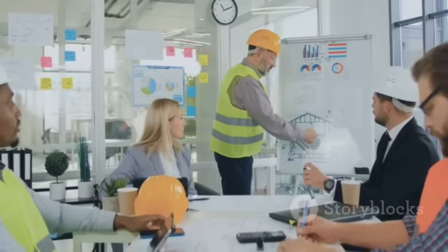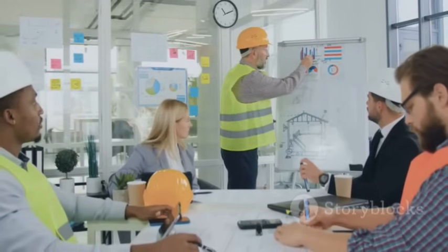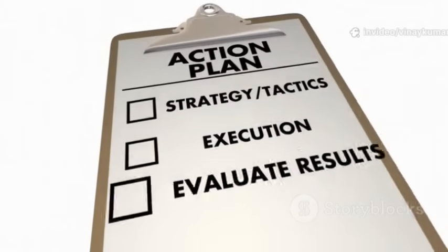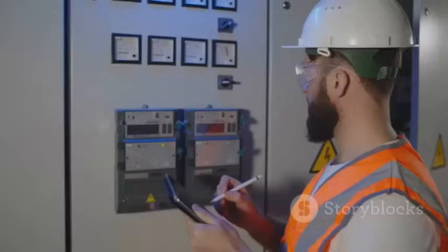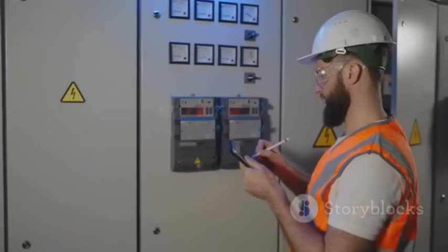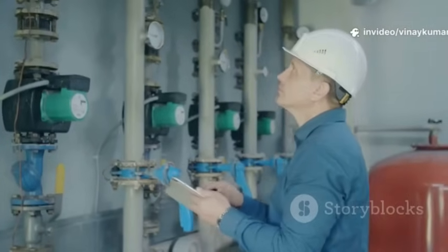It quantifies, or at least qualifies, the likelihood and severity of potential events, allowing the team to focus on the most significant dangers. The output of the PHA is a list of recommendations to reduce or eliminate the identified risks. This might be adding a new safety interlock, rewriting a confusing procedure, installing a better alarm, or changing a material of construction.